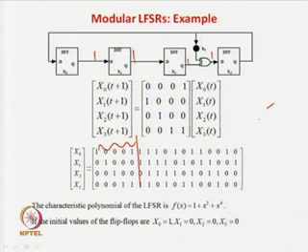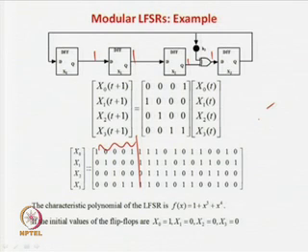So the same case existed in the standard LFSR, that we have to set the seed vector in such a way that very quickly we can get the required test patterns. In this case let us assume that the person has assumed that maybe this or this may be his important test vector, so he has given this as the seed vector. Now, let us see how we get these patterns.